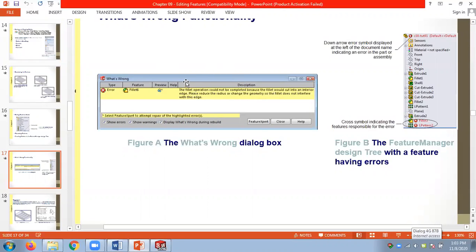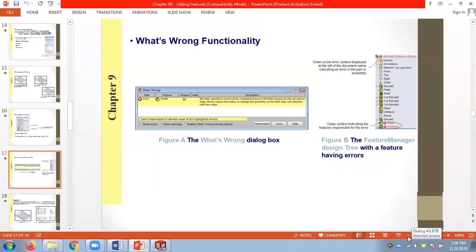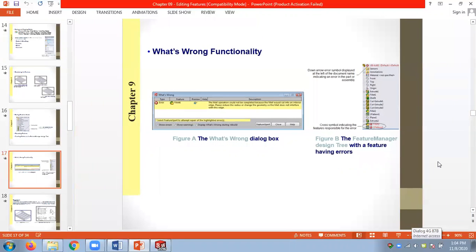So if the model is very thin, you cannot have big radiuses in the fillets. Please remember those operations. If you have these red areas, always correct them and go forward. Otherwise you will face a lot of problems in the future.